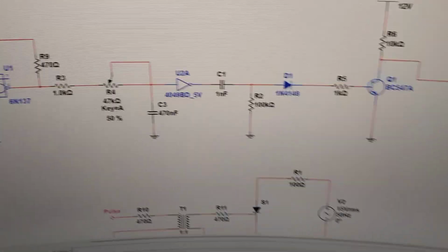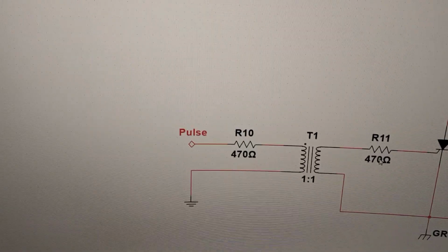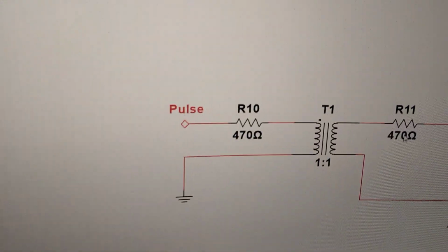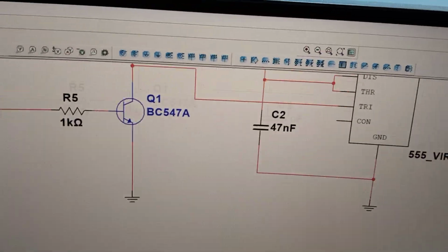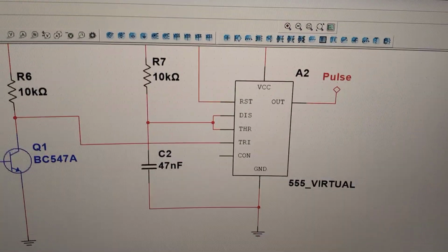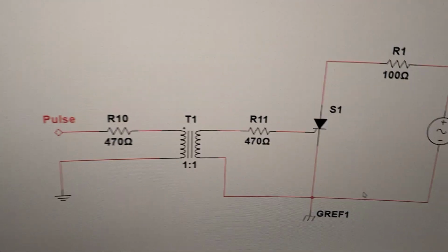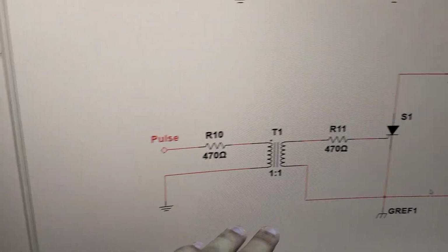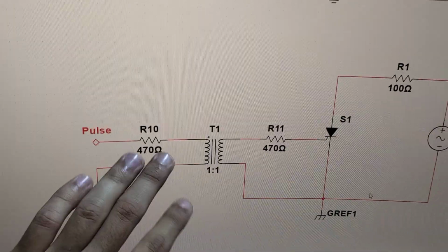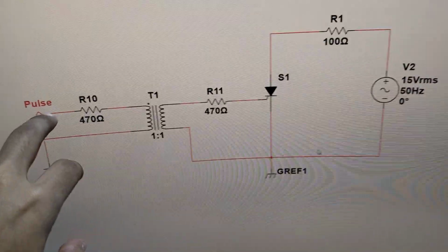Now moving on to the power circuit here, which is smaller and shouldn't take much time. There are what they call pulse transformers. They're small 1:1 transformers, and again same thing, to isolate our monostable side, to give this pulse to the thyristor. Again, this is a low power circuit, and we want to keep it isolated from the thyristor, which is a high power device. Then just a resistor to limit the current, because after all it's DC. If you don't use a resistor, it's going to get shorted, and that will be messy. So this is not an AC signal we're giving here.